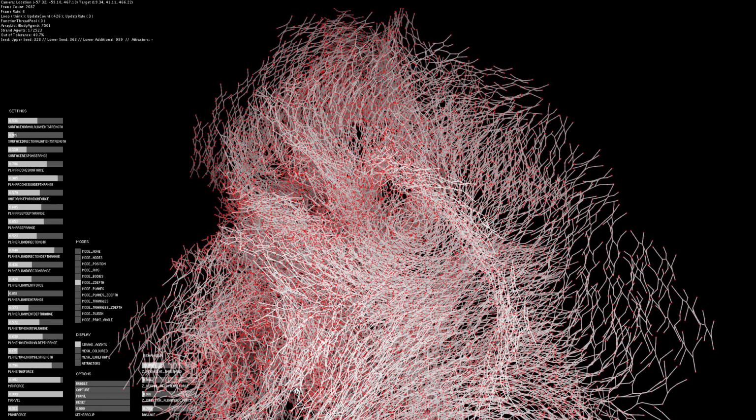And this entered into a feedback loop where what he eventually realized was, in order to accomplish the real-world fabrication of these things, you have to take into consideration the material properties of what you're going to be working with. So in this case, the project for the Centre Pompidou was made using SLM printing, which is powder-based printing. We did it out of aluminium, so this was a piece of metal. And the assumption was that with SLM printing, there wouldn't be a huge amount of constraints. Mainly, you wouldn't have to worry about draft angles or cantilevers or anything like that. Turns out we were fairly wrong about that assumption.